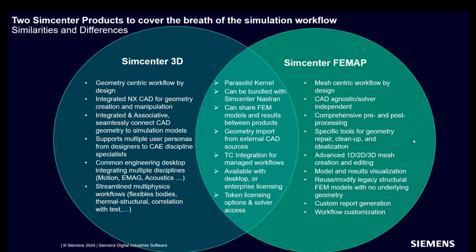because you think about it for a minute. If you've got a geometry-based tool where geometry is master and everything relates to that, it kind of breaks your data model if you bring in just a finite element model. In order to make that work, you would have to go back and recreate some geometry on that mesh in order to have a basis to complete that workflow. Some of those things are available in Simcenter 3D. They're just probably a little bit more difficult to use in that way.